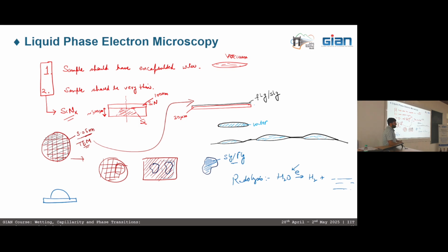That kind of precision is required again when you take it out from the liquid, because when we take it out, the surface tension tries to pull it back inside, and that will again be a problem. Then because we have etched away the copper in APS solution, it might have certain impurities, certain copper deposits might be present there. Then you have to wash it using DI water several times, maybe 3 hours, 5 hours. That is also one of the very critical steps that you must take care of.